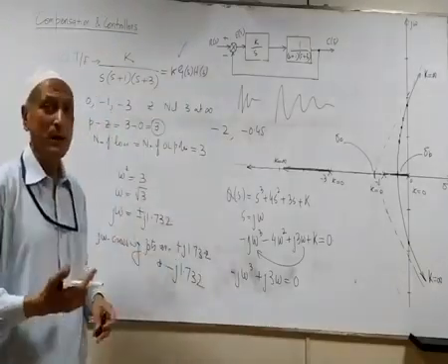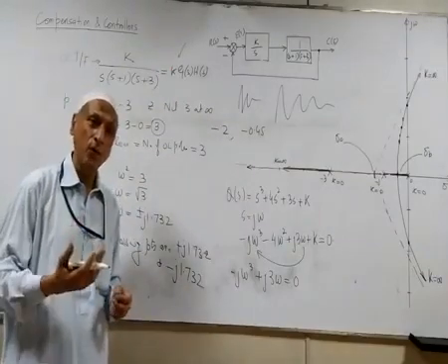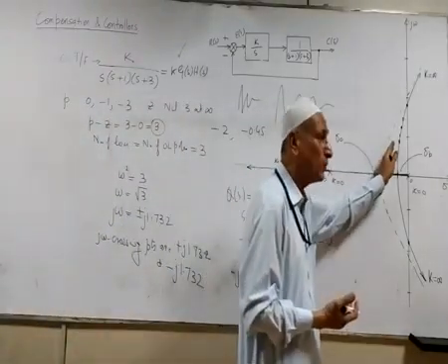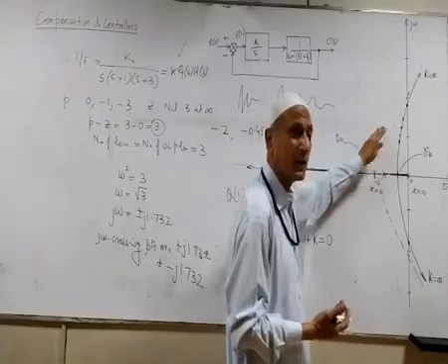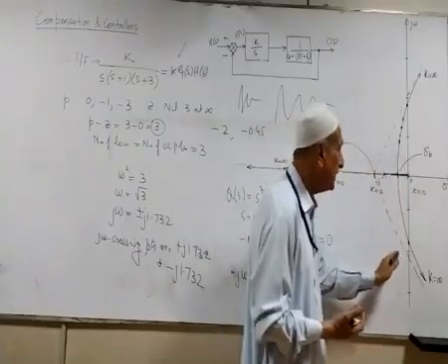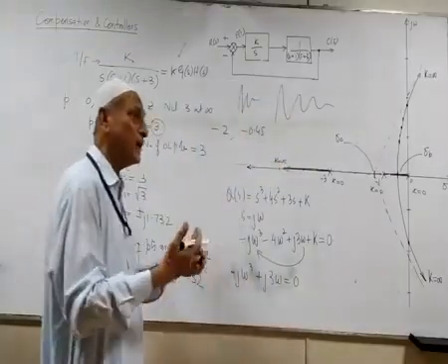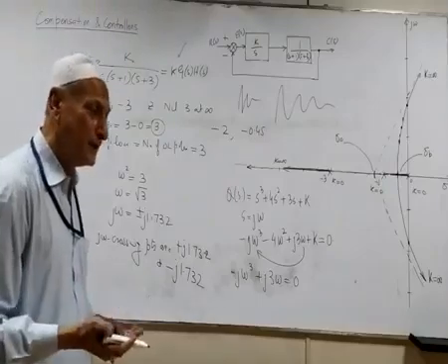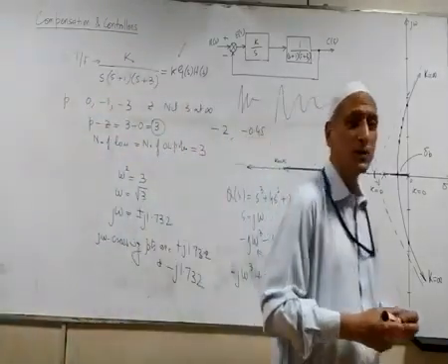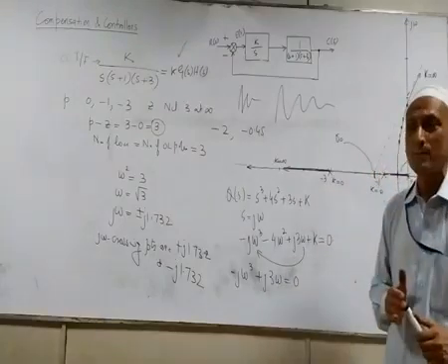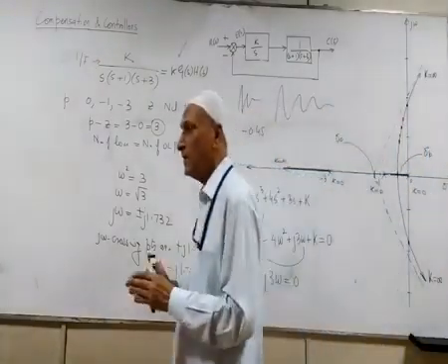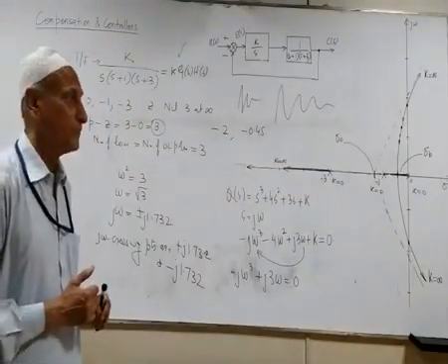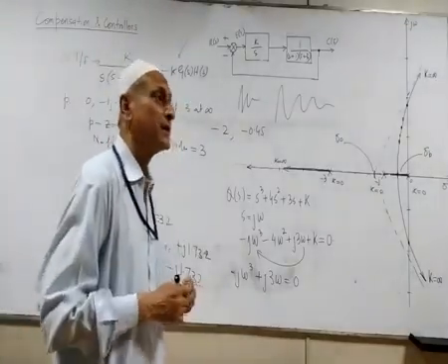So this is a simple gain integration we are performing on the plant, and that leads the system to have a root locus which is now shifted towards the right and then going into the unstable region. In fact, we have deteriorated the system's performance. So adding or incorporating a derivative control will improve the transient response. If you incorporate integral control, it will deteriorate the transient performance. Now, something good about integral control as well.